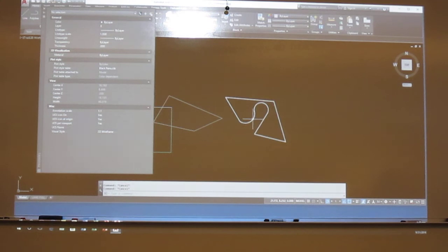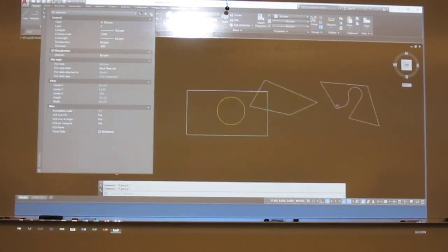There's also a subtract command. So like here, let's say I wanted the area of this whole thing minus this part, this hole that I'm cutting through it. Maybe this is a concrete bridge abutment, and that's going to be a culvert that's installed in it. So how much concrete do I need? I can get that answer really quick with the area command. If I type in area, I'm going to click around through the object. That gives me that area.